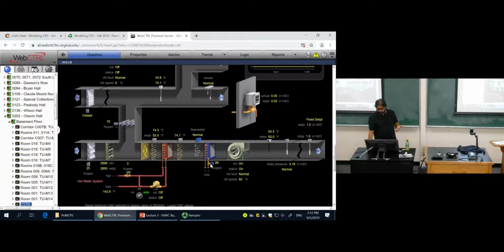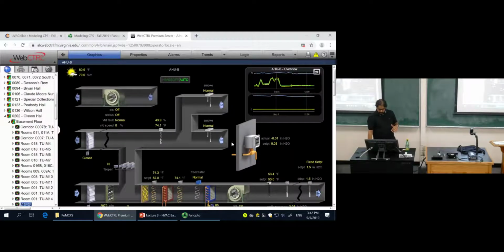We can regulate how much flow we want at this heat exchanger. It's 86% valve position, which also tells you this local PID state. Then there's a fan, which can operate between 0 to 100 sort of RPM range. So we have conditioned this air to be at 55 or roughly 55, 53 to be exact. It's getting sent to 018 and other zones too. And then air comes back again at around 75 from these zones.